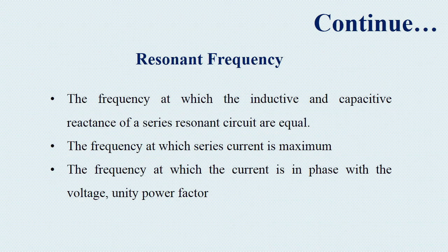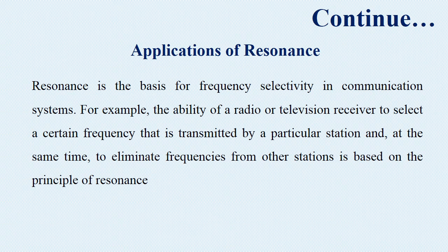And at the resonant frequency we have only the resistive element, and we know that for a resistive element the current is in phase with the voltage of the circuit, so the circuit will have unity power factor. Resonance in an RLC circuit provides a kind of selectivity for a given particular frequency.